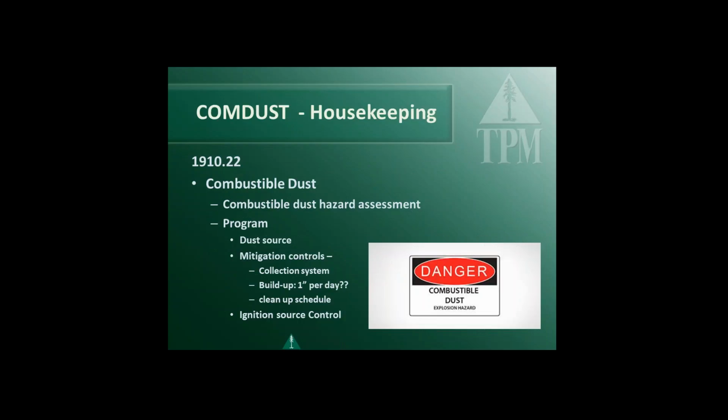Leading into the combustible dust, that's where I've seen the citations for combustible dust from our inspectors, basically under this housekeeping. You've got dust under 420 microns, under 25% moisture content, here's the citation: it's a buildup of more than 1/8 of an inch. So that's where it comes in, staying on top of this. Most of the citations are over 4 or 5 inches, because there's some gray area, so they don't want to cite you for over 1/8 of an inch. They don't want to have to fight all that. So if there's a couple inches, that's where I see the citations, especially if it's fine dust.